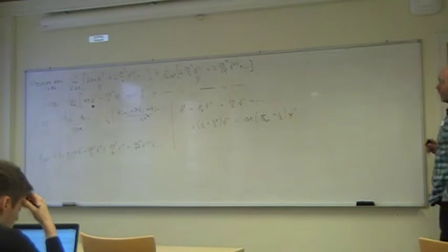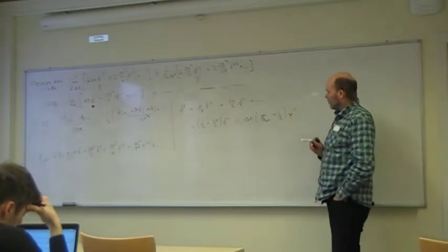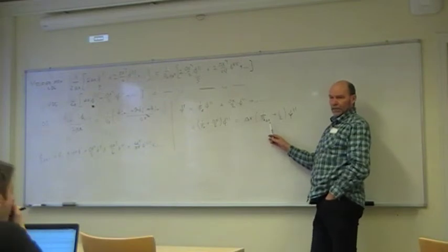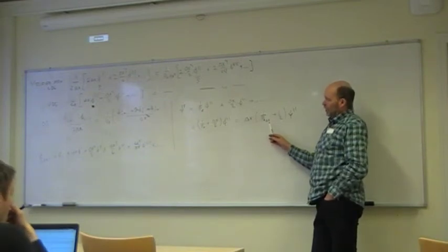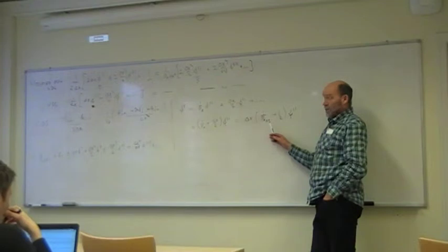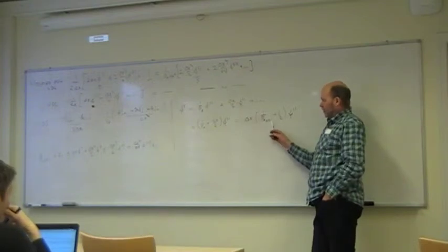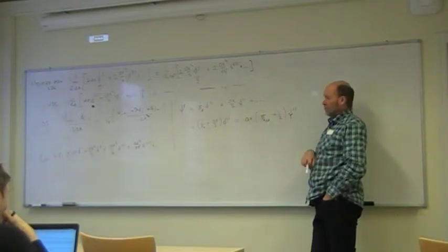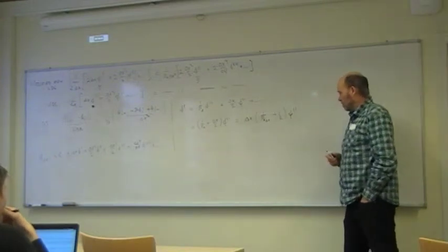For the central scheme, the local cell Reynolds number had to be 2 or smaller. But for the upwind scheme, it could be anything. But here you see what happens. If it is 2, you have double the viscosity. So very bad idea, of course.